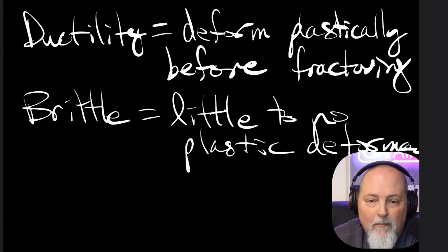So ductility is important because ductile materials give us a little bit of warning before failure. That's why highly ductile metals are desired in our piping, our reactor pressure vessel, our fuel cladding, all these things that see all this thermal stress and vibration all the time. And the slip matters here.